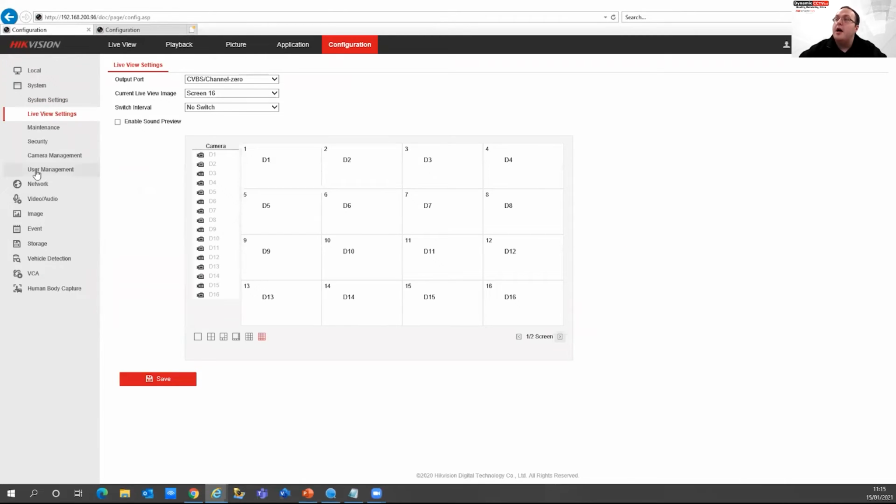There's quite a few useful things now through the web front ends of the NVRs. You can actually configure the local monitor outputs remotely through the web front end of the recorders. So you can see we've got the output port here. We can go HDMI, and we can actually change this layout. I can go in and remove the cameras that I don't want to display there, and I can just have the bottom 3 rows displaying, or I can even change the actual view itself. So I can set it to a 4-way view for the HDMI output.